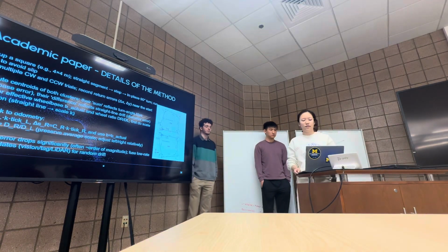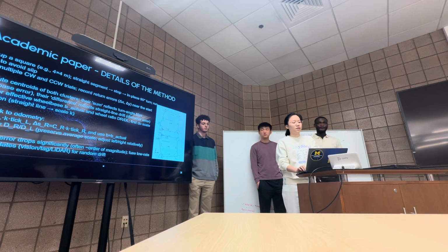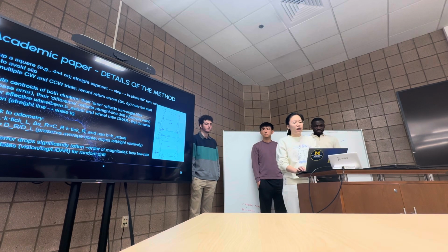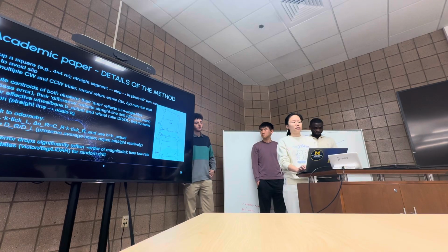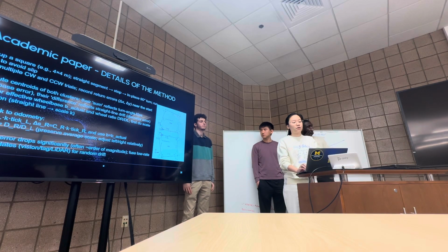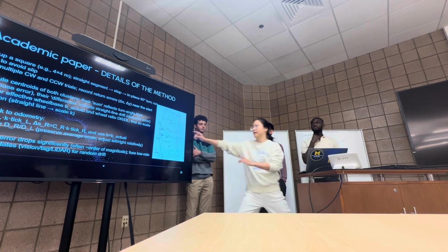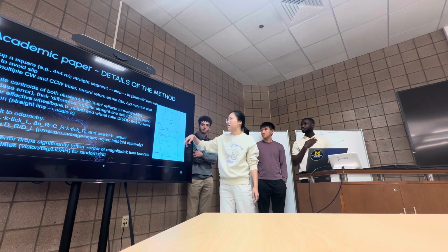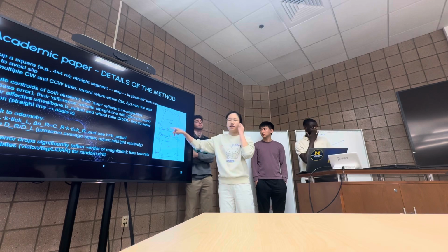I will present the details of this method. First we set up a square path, like a 4x4 meter square, where the path is a straight segment, stop, and then an in-place 90 degree turn. We run the robot slowly to avoid slip. Then we run multiple clockwise and counterclockwise trials and record the return errors delta x and delta y near the start point. Here, this is the start point, and after one square pass there's a gap between the end and the start.